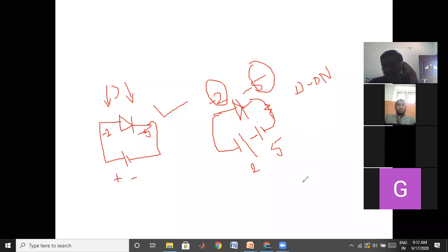While you study EDC, you may learn that when you connect the positive terminal to the anode and the negative terminal to the cathode, the diode gets on. I have changed that definition a little bit, and defined that positive means greater voltage. The anode should always be connected to the greater potential, and the cathode to the lower potential.